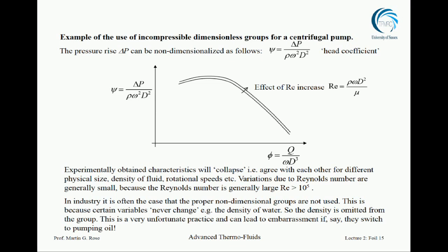There are exceptions, of course. The MIT machine at 4 millimeters diameter has such a low Reynolds number that it's very unlikely to be turbulent. So it's a laminar flow, and laminar flows do a very wide range of interesting four-dimensional flow fields with separations and eddies and reattachments and so forth. The efficiency always drops off at such low Reynolds numbers, and the flow is entirely different.